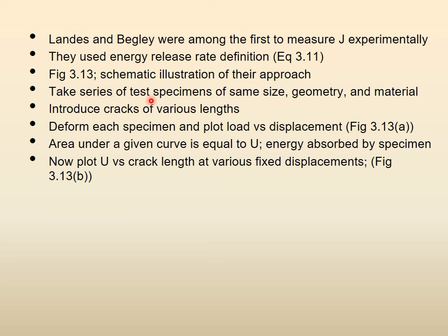They take a series of test specimens of the same size, geometry and material. This is still tough experimentally because they have to make many specimens of the same material of exactly the same size and geometry. They introduce cracks of various lengths. They deform each specimen and plot the load versus displacement.